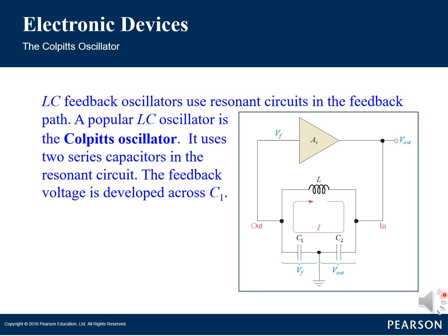The basic circuit of an LC feedback oscillator consists of an amplifier, an inductor and a capacitor connected in a feedback loop. The inductor stores energy in a magnetic field, while the capacitor stores energy in an electric field. The amplifier amplifies the input signal and generates an output signal, which is then fed back into the input through the feedback loop. The inductor and capacitor form the frequency-determining element of the circuit, which determines the frequency of the oscillation. A popular example of an LC oscillator is the Colpitts oscillator.